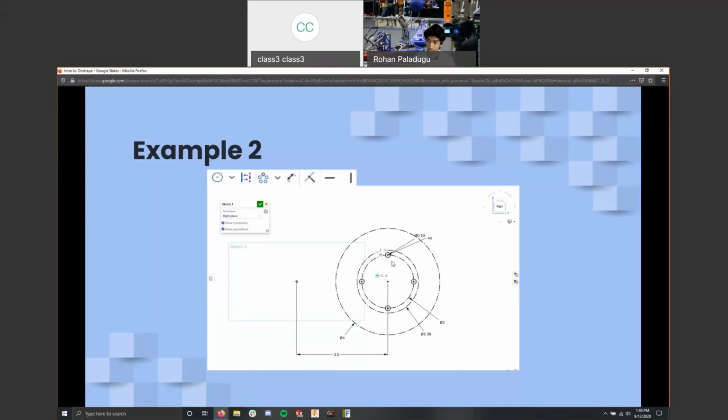This was me actually selecting a vertical constraint between the center point of the main shooter assembly and the center point of the motor mounting hole. That allowed me to make sure this was correct and there were no deviations anywhere. And then there are a few implicit coincident constraints between the 3 construction circles that I drew.